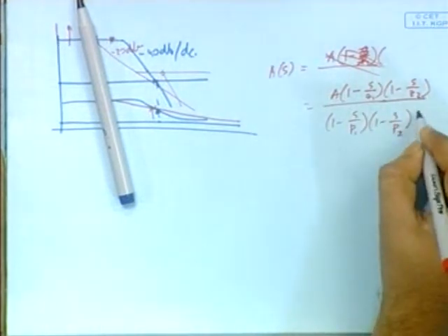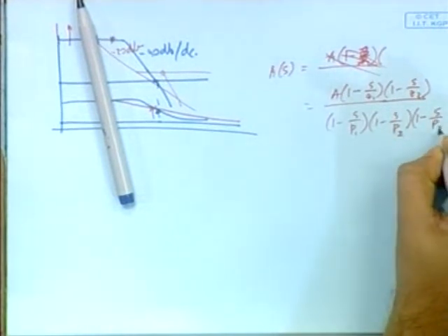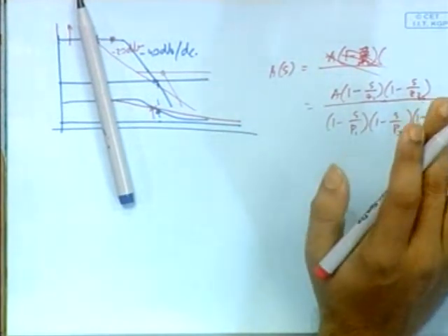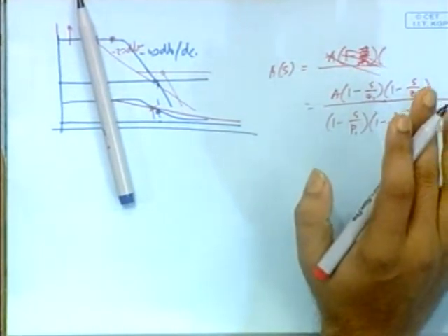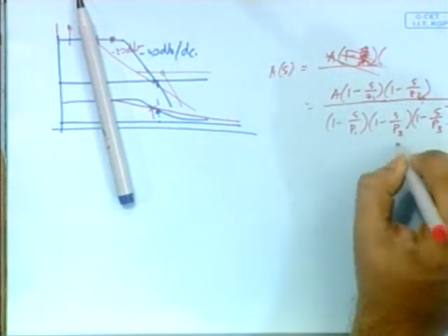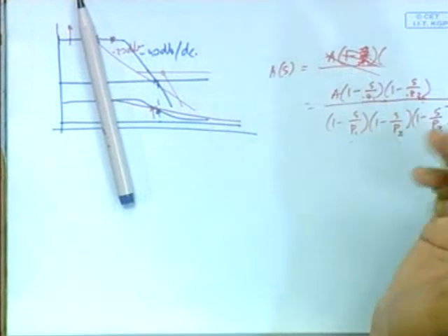I am a bit confused, so don't get hooked onto that type 1, type 2, type 3 terminology. Check it for yourself. So there will be 3 poles and 2 zeros. This is the most common compensator that we use in most on-chip buck converter design. And there you will have to place these poles and zeros accordingly to get your proper phase margin.